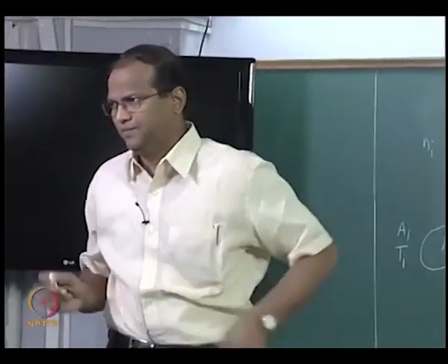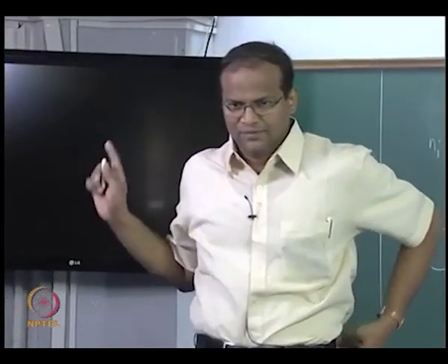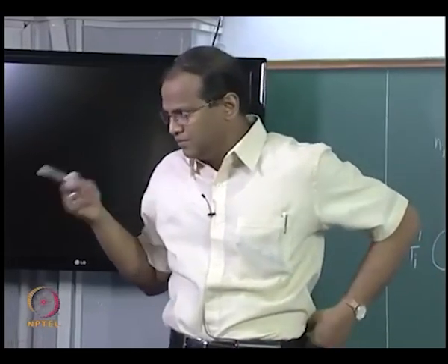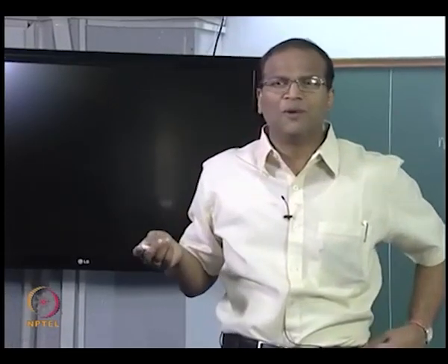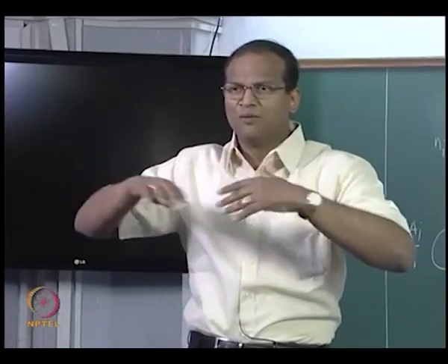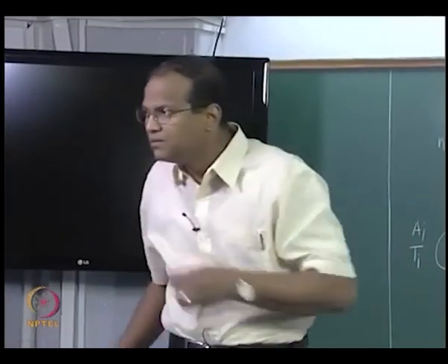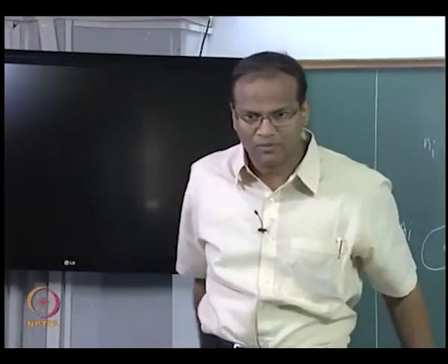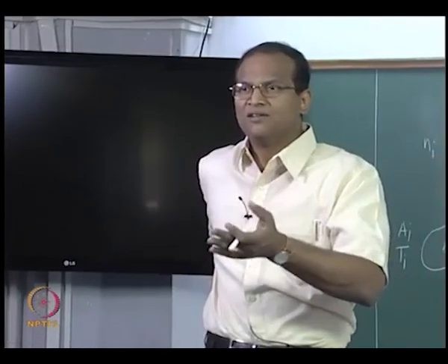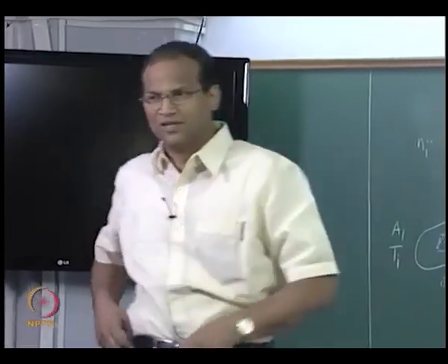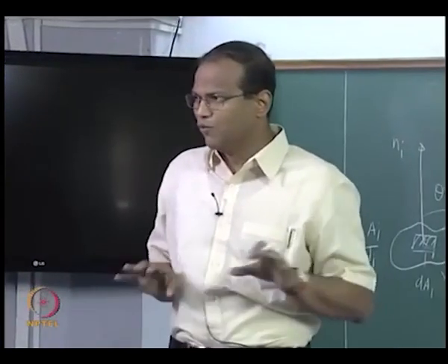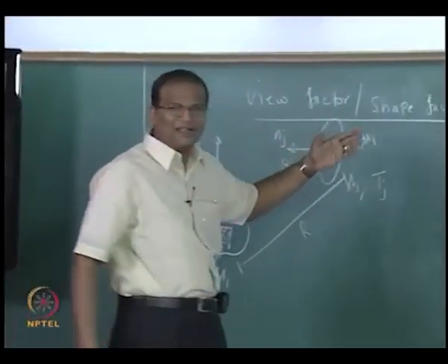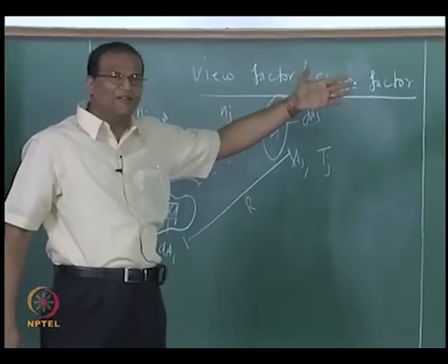Now you can see that view factor is not easy, right. If you want to subdivide, it involves a lot of computational power, okay. But one good thing is, if the geometry is fixed before you start your heat transfer problem, your view factor calculation is done. Your CFD solver is not like that. Every time the velocity will get updated, it is a non-linear problem. Here it is like your mesh. If people are using Fluent, in Gambit you do it once and for all, unless your geometry is changing. So if the geometry is fixed, you can determine the view factors once and for all, okay.